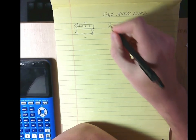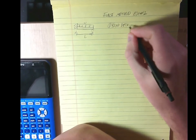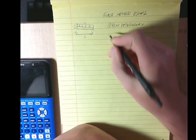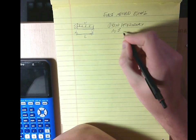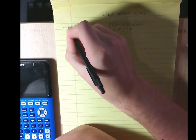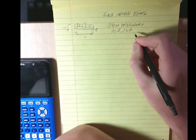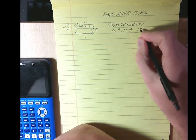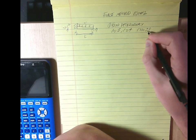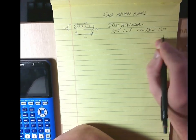So first thing we do is we find the determinacy. For this, n is equal to 1, r is equal to 4. We know this again because that's fixed, and that's a roller. There's our 3, that's the fourth. And from this, we know that r is greater than 3n. Therefore, it is statically indeterminate to the first degree.